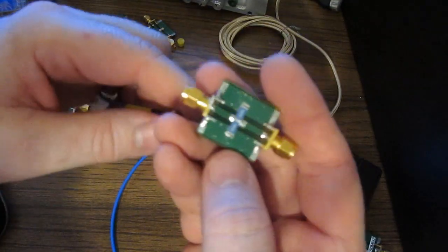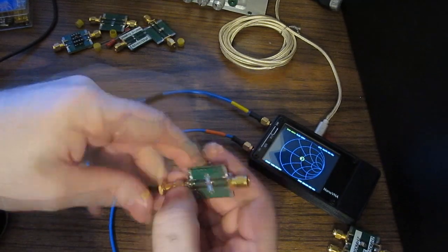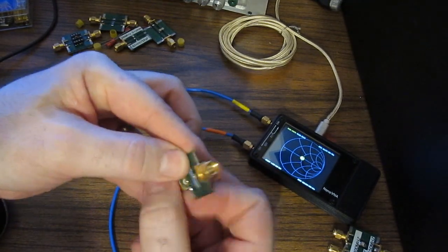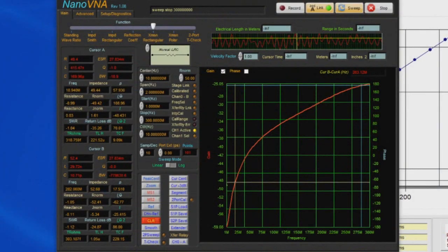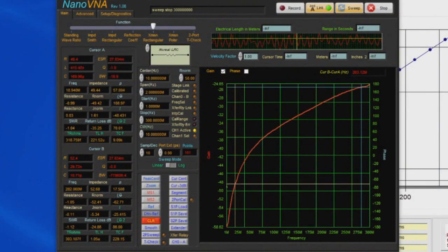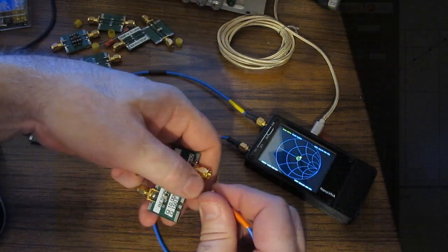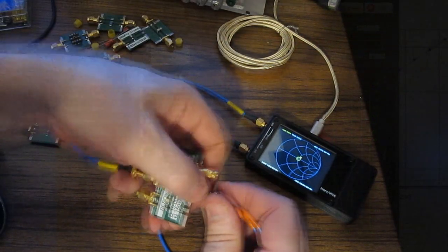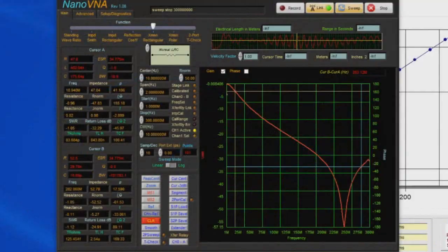Let's just start out. This will be our two 50 milliohm resistors in parallel. Again, we're expecting this to read roughly 25 milliohms. Looks like we're in the ballpark, so 29, 26, there's a 23.8. Let's go ahead and insert our capacitor. Again, we're looking for roughly 28 or so milliohms, probably a little higher, 37,